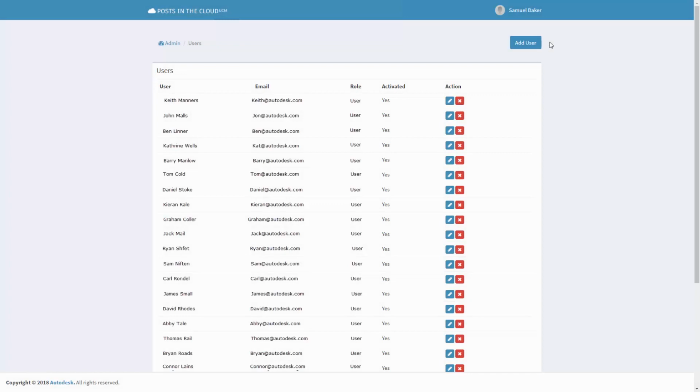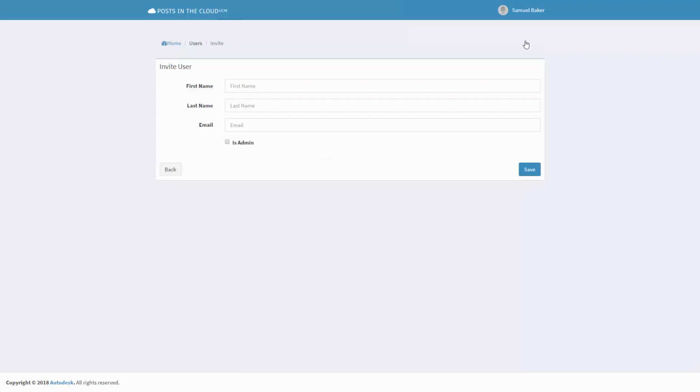To allow additional Powermill programmers to access the post-processor files, they must be added to the post in the cloud interface. This is done by creating a new user, entering their name and email address, and giving them user status. The same interface allows users to be deactivated.